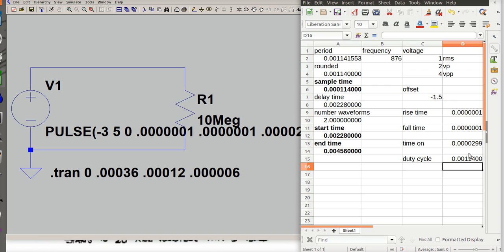What I'm doing here to get that is I'm taking this duty cycle, and I am saying my on time is going to be a very small fraction, one little point of that. And then my rise time and my fall time will be the angle. So they're going to get long, and my time on is going to get short. This is exactly opposite from the square wave, and you'll see the effect in a minute.